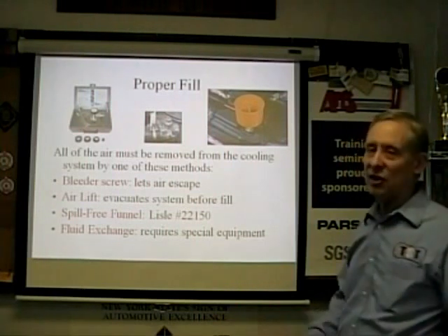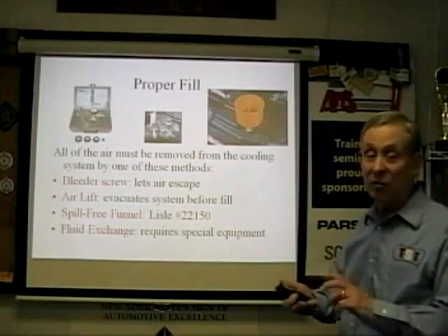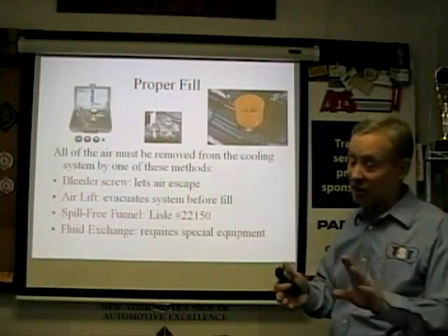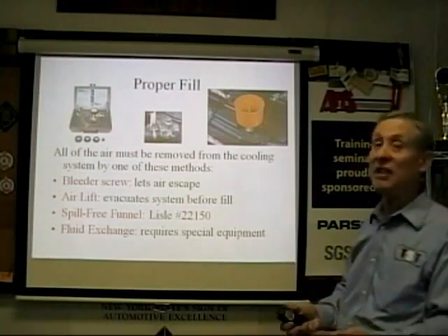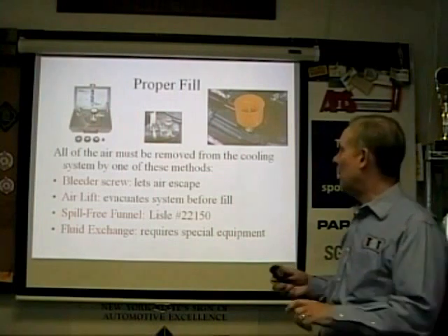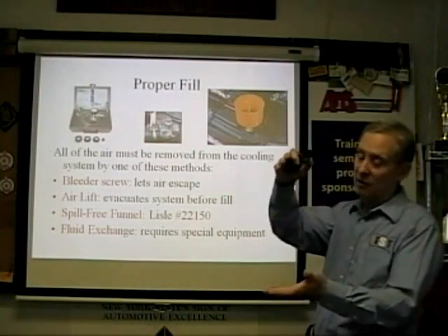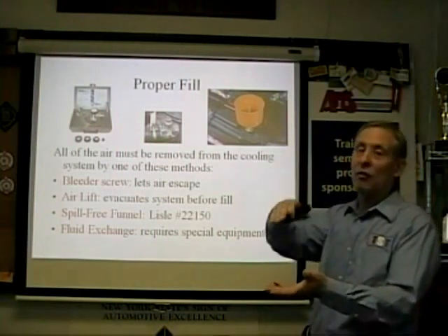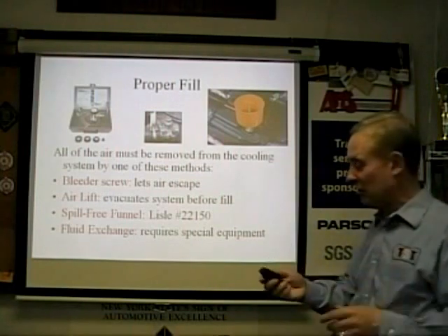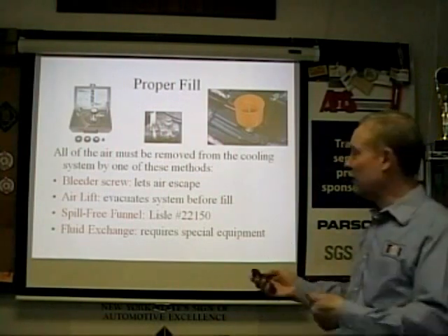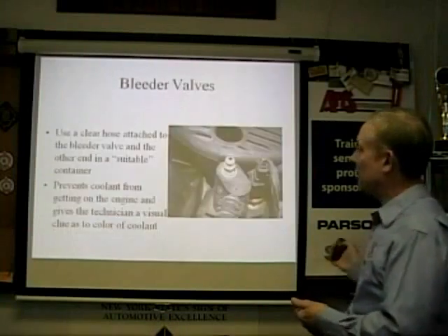Proper fill, you've got to make sure that you bleed it out. The bleeder screw, air lifts are good, or any other technology like that that cleans out all the air. Use a spill-through funnel that puts a fluid cap over your system so it pushes all the air bubbles out. The idea is fill it completely, get all the air out, and make sure it's clean.